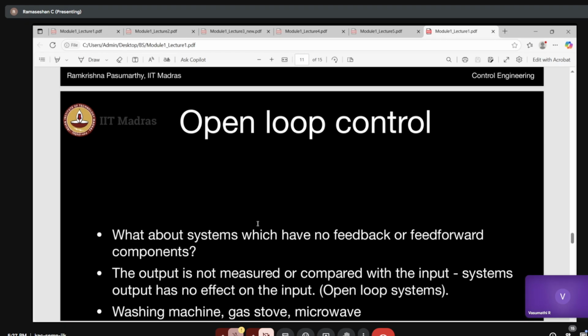Yes, sir. Okay, so imagine this. Every system has some time constant. It takes some time to respond. For example, an RC circuit has its own time constant, the product of R and C, or 1 by RC, right? That tells you on what time scale the system operates. Mechanical systems operate in seconds. Electronic systems can operate in millisecond time scale if they are of sufficiently high frequency. And thermal systems operate on minutes. You can't change the temperature of a room within a second, right?